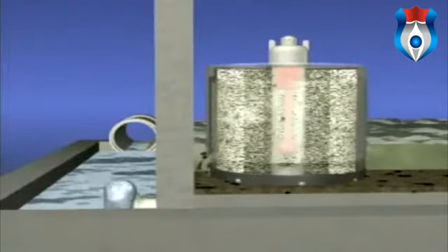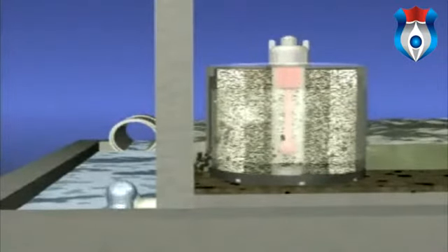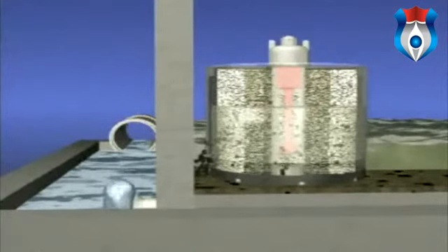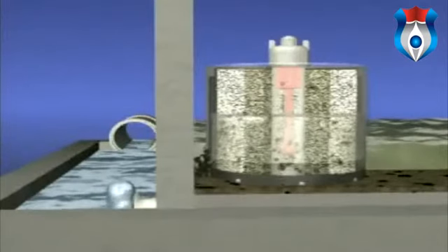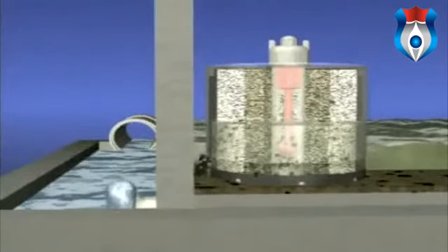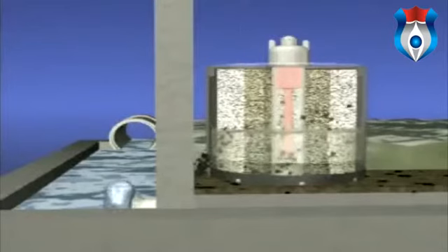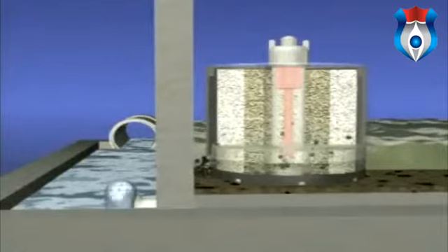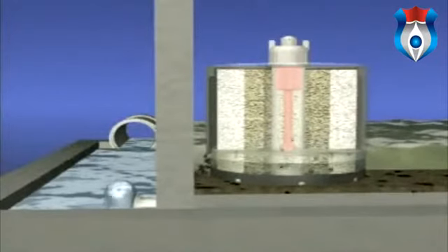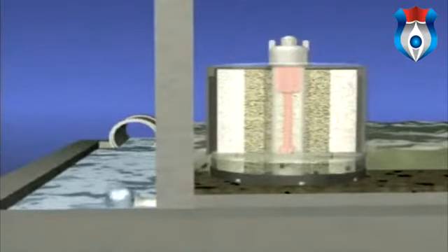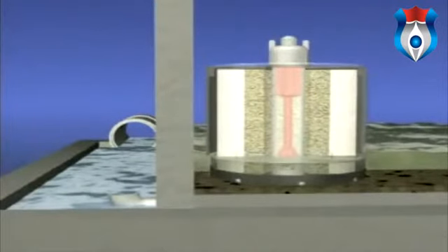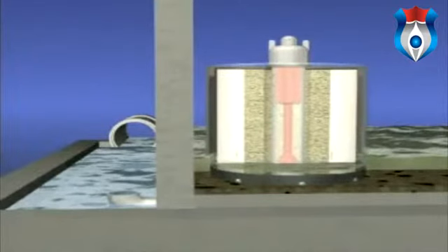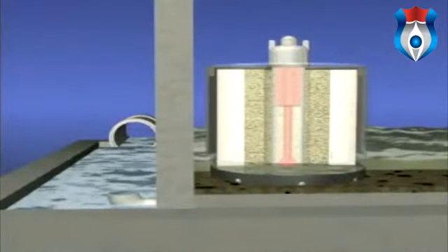A hanging water column will remain under the filter cartridge hood until the water level in the vault reaches a series of scrubbing regulators on the bottom of the hood. As the water in the vault continues to drop, air bubbles rush through the regulators into the cartridge as the water under the hood is released. The bubbles agitate the surface of the filter media, causing much of the accumulated sediment to drop to the vault floor. This patented self-cleaning mechanism also increases the effective life of the filter.